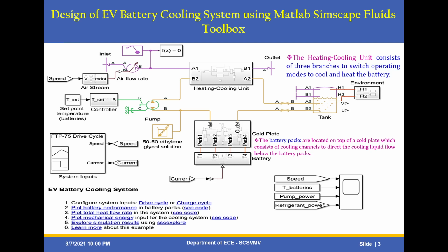Here for each and every block you can analyze the simulation output. For example, what is the controller input, what is the controller output, what is the drive cycle input, the system inputs, what is the battery state of charge and speeds, and the pump power, refrigerant power, all things you can see via this interactive Result Explorer, SSC Result Explorer.